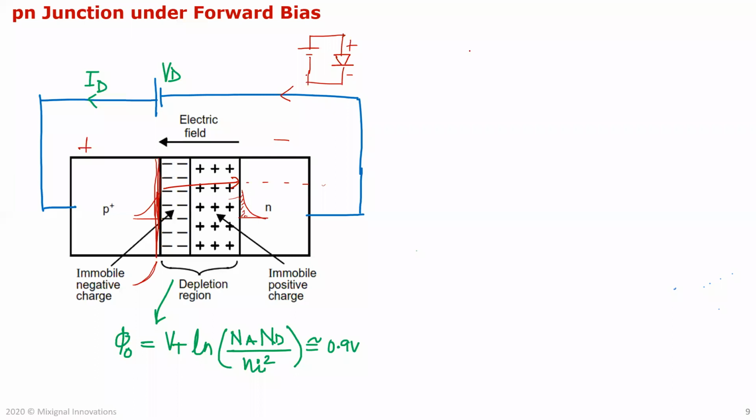Just to explain what diffusion and drift are: if you have a free electron and you apply an electric field, like some material, you apply a positive potential and a negative potential, you get an electric field. You get a force Q times E, and this electron moves in the other direction. Obviously it's got Brownian motion, and moves toward the other side of the potential.